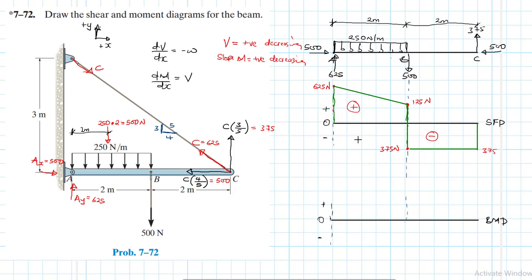So the shear force rate this time around is of degree 1. This is a linear function. Then you expect the moment function to be of degree 2. So this is going to be a quadratic function. But it will be positive in the region A to B, but decreasing slope. Right. So it will be something like this, decreasing, decreasing, decreasing up to that point. Right. That's the point where we have the maximum, right? Okay, we'll calculate this maximum later on.